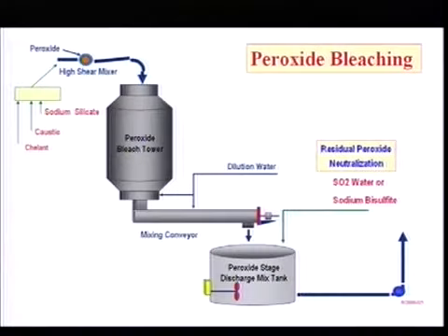And also if you are mixing with oxygen, you are dumping from top to bottom, oxygen can go away and stay in the top, so you won't have efficient mixing. So there you use the upflow tower. Where do you use a downflow tower? For peroxide. Here after mixing, you can just dump it.